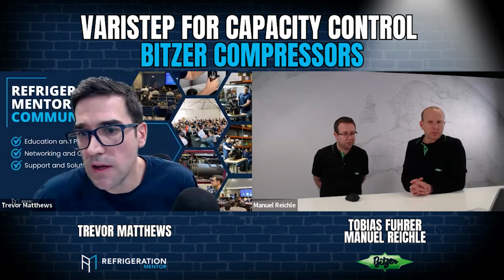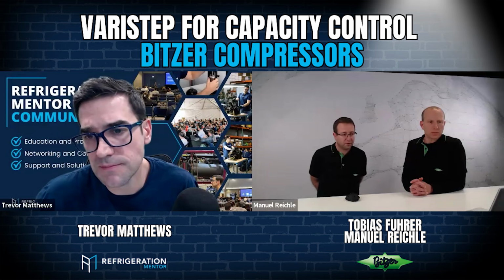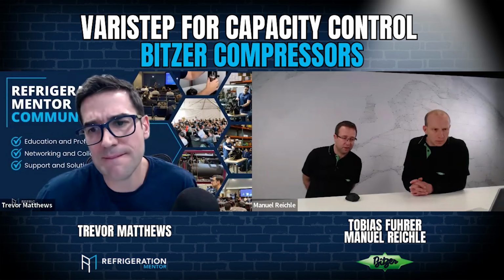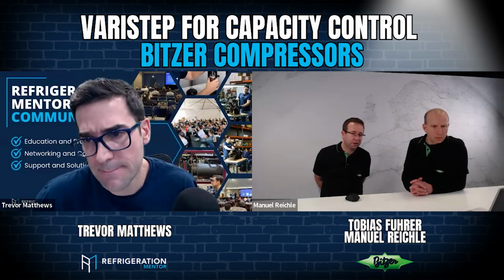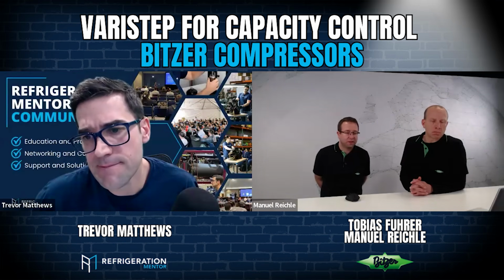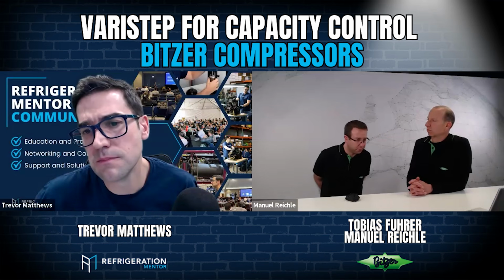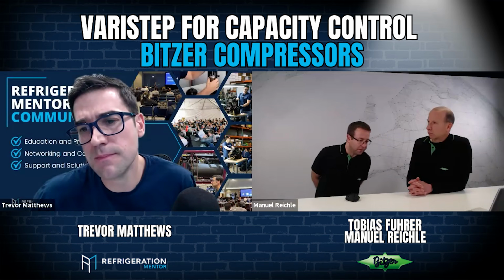Perfect. Is Varistep now available for all 2-cylinder and 4-cylinder CO2 compressors? 4-cylinder, 6-cylinder, and 8-cylinder. In 8-cylinder, we only run the staged configuration, but it is available there. 2 cylinders, transcritical are possible on request.